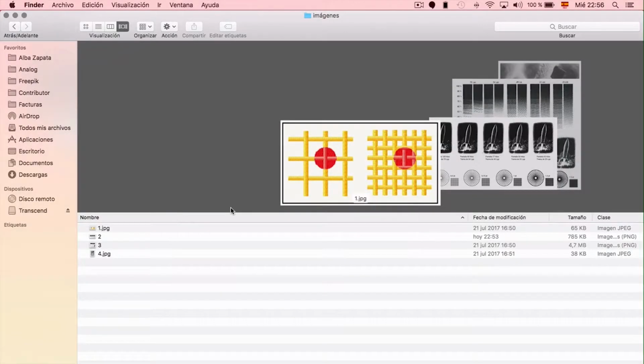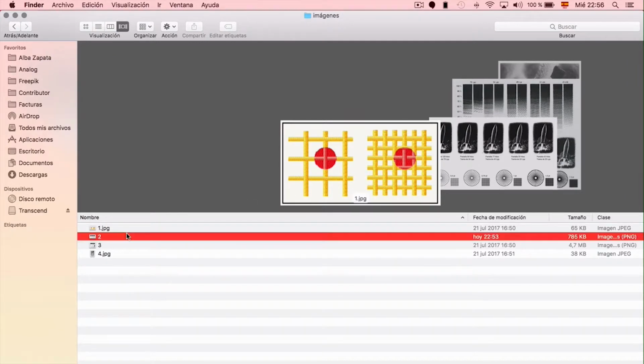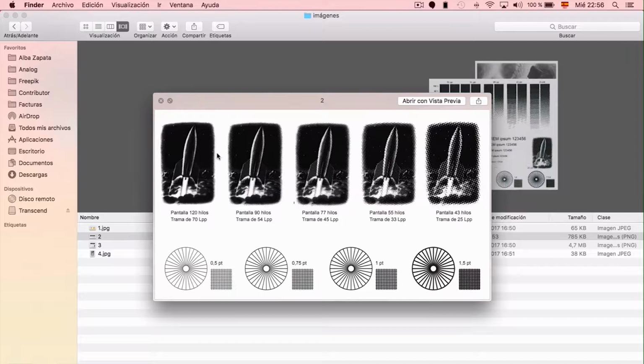This depends on the weight of the mesh on our screen. There are meshes with different weights. The heavier it is, the smaller the gap between the threads and the more details you can add, as the points are smaller. A heavier net is okay for printing sheets, but not really if we're printing t-shirts. Then the ideal weight of the screen's fabric would be 43 threads.